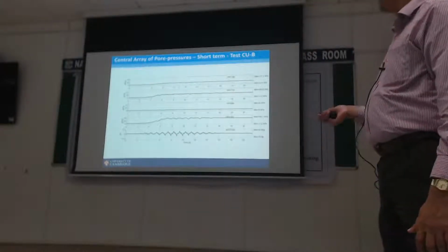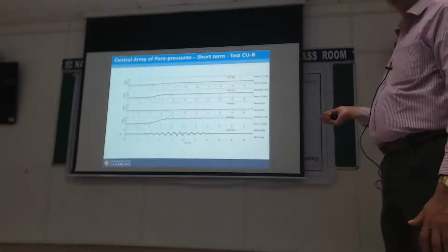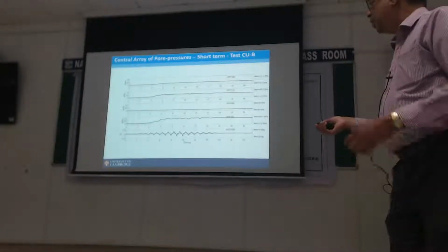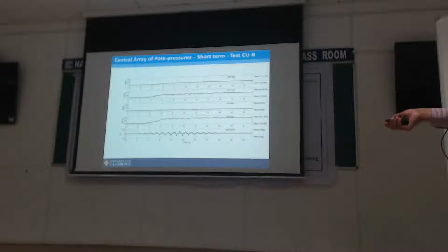Of course, whenever you do this, some instruments, like this PPT, didn't work; you'll always have some instrument failures. But you can see for this type of smiley face motion, the pore pressures take a little while to build up because the motions are small here. They get to this full liquefaction level and then they stay, and you get these suction spikes, which is consistent all through.